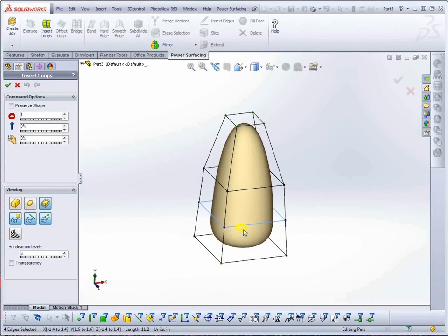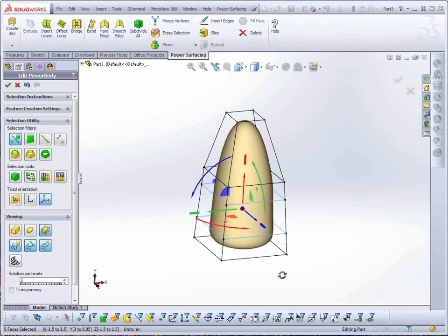Set the number of loops to 2. Try adjusting their position with the directional gizmo to slide them, or use Pinch, using the round end of the directional gizmo, to move them closer or further apart from each other. You can also affect the parameters directly in the Command options. Once again, press Escape, OK, or right-click to finish the command.